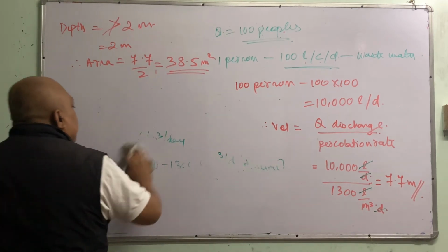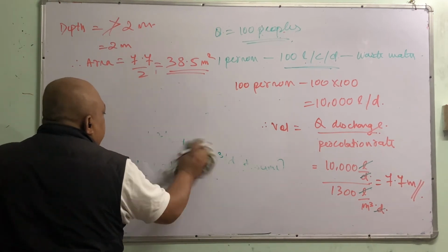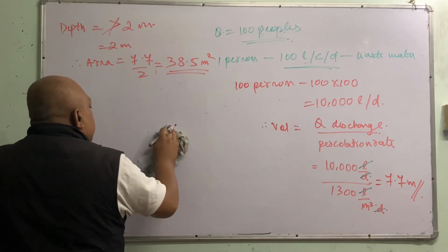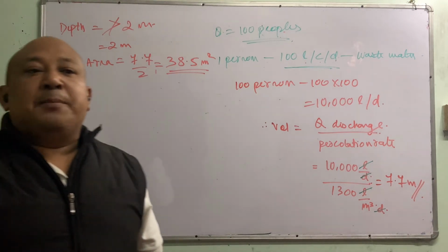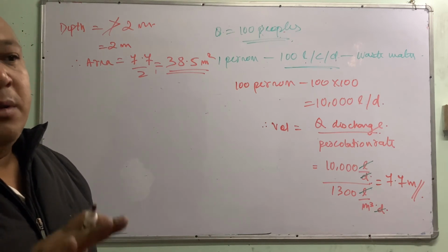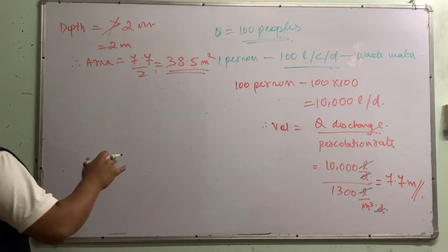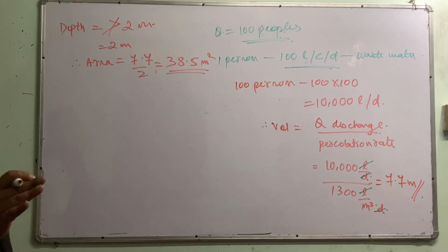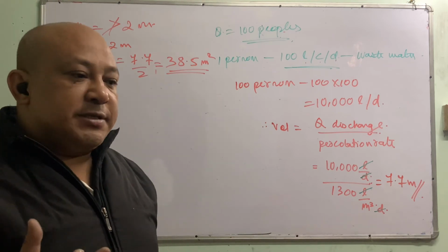Next, if you make the length into breadth, it is of no use, because here it is not going to get to any outlet. Everything is going to get percolated, all the liquids, and once the sludge becomes very thick, that will stop the soak pit. In a septic tank we remove the sludge, but here we are not going to remove it, it's going to lie over there in the soak pit. So the length into breadth is not necessary.